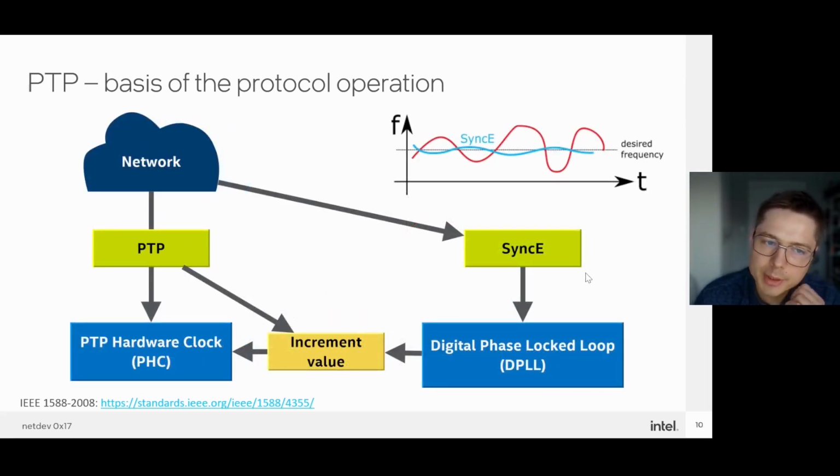The solution to this problem is using Synchronous Ethernet to stabilize those clocks. This protocol can calculate the best clock source and recover from that link, and actually synchronize and feed it back again to the system. It needs special hardware which is called DPLL, but more on that a little bit later. Such a hybrid system with some improvement to the PTP can achieve sub-nanosecond synchronization. The White Rabbit project is a good example of such implementation.